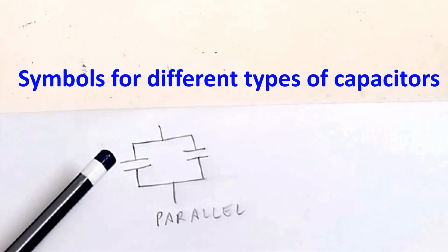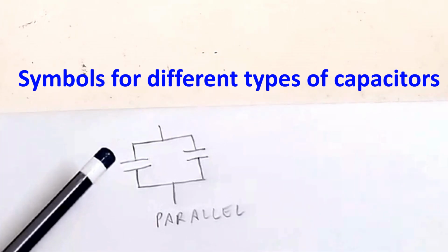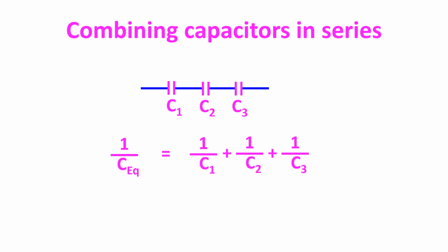If you combine in series, the capacity will be lower. While capacitors are combined in parallel to obtain higher value of capacitance, as in filtering circuits, series connection is to achieve higher working voltage, though the resultant capacitance will be lower.